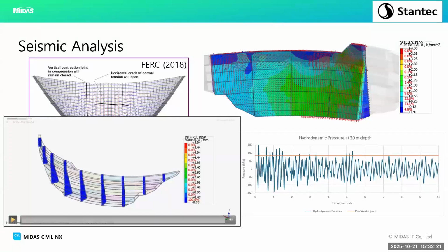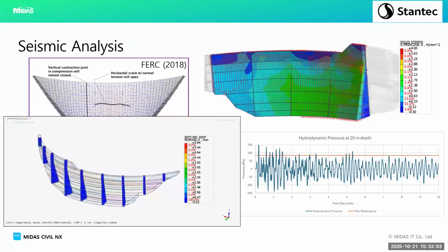So this is going to be the relative opening, and the shear keys that we saw previously were approximately 150 mils. So now we can look at it and say, are we getting 175? What are we getting? And this is with the zero tensile strength interface. You can see we do get some opening at the top portions, but it's probably around 2 mils or something, quite low and well within the capacity of the shear keys.